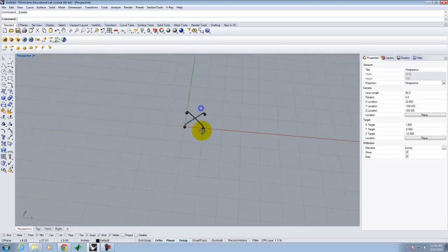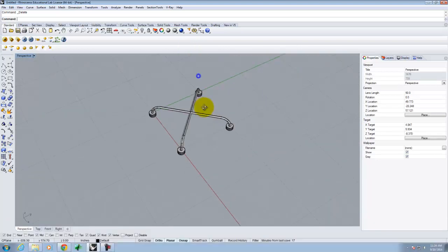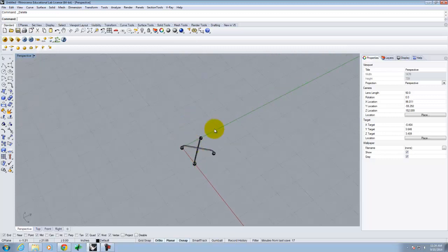The next piece of the puzzle is I'm going to create basically a spire that sticks up with a little donut on the end that can accept a cable. And so I have drawn on the back a breakdown and a side view, projected view of what this little piece looks like. You can see right here, I've got an overall dimension of 2 feet. And then I've got 1 foot 9 1/4 and so on. You can build it based on that piece.